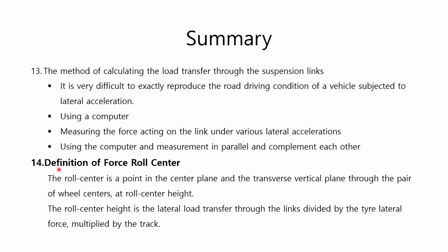The force roll center can be defined as follows. The roll center is a point in the center plane and the transverse vertical plane through the pair of wheel centers at roll center height. The roll center height is the lateral load transfer through the links divided by the tire lateral force, multiplied by the track.